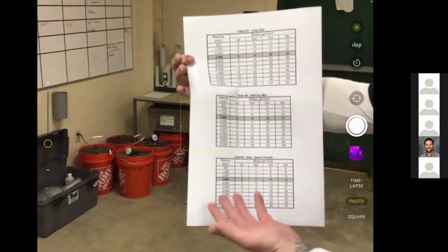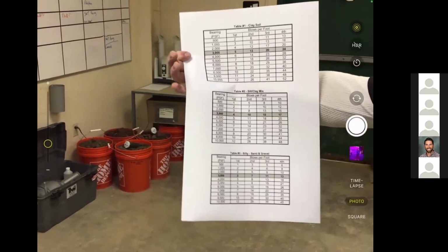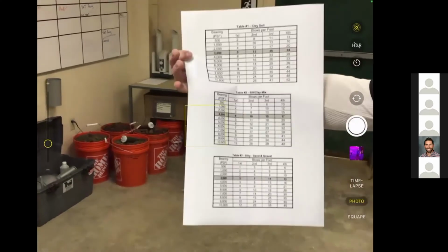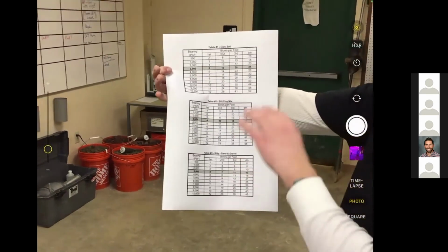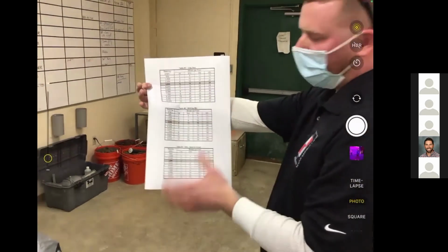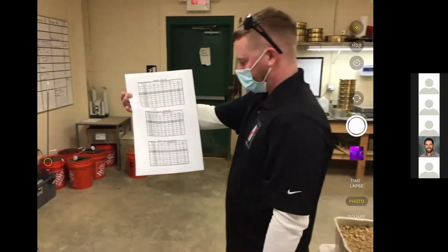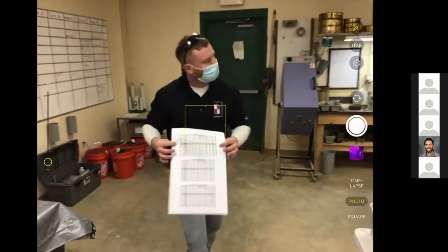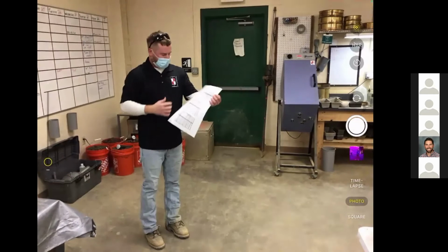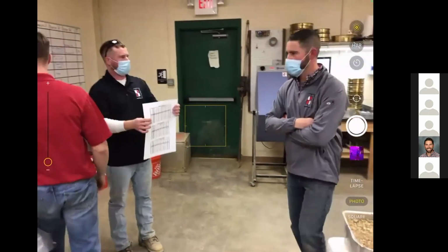If we have issues and we do not reach the strength of that soil, that's when we will remediate, we'll over excavate, and we will backfill appropriately with suitable material to achieve the strength of bearing that we need for that building. That's about what we do for bearing.